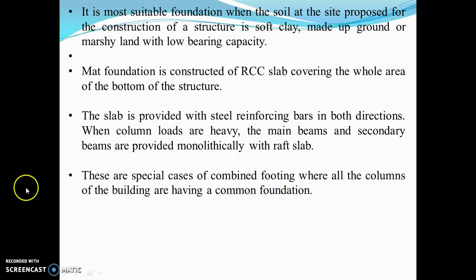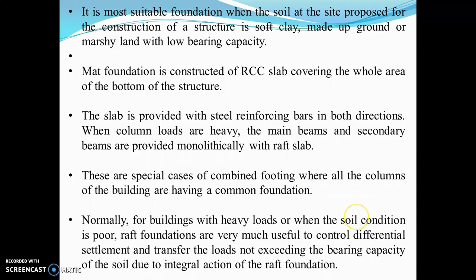These are special cases of combined footing where all the columns of the building are having a common foundation. Okay, this type of foundation has one common foundation for all the columns together. Normally, for buildings with heavy loads or when the soil condition is poor, raft foundations are very much useful to control differential settlement and transfer the loads not exceeding the bearing capacity of the soil due to integral action of the raft foundation.